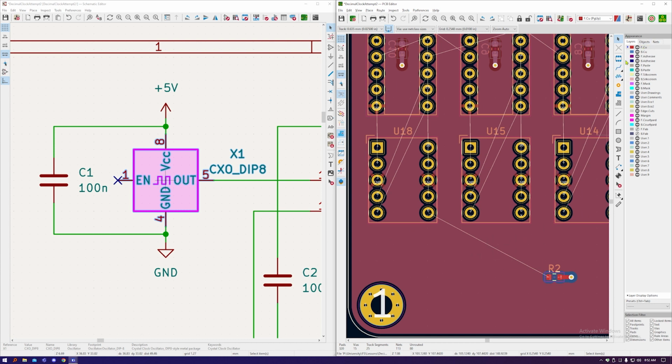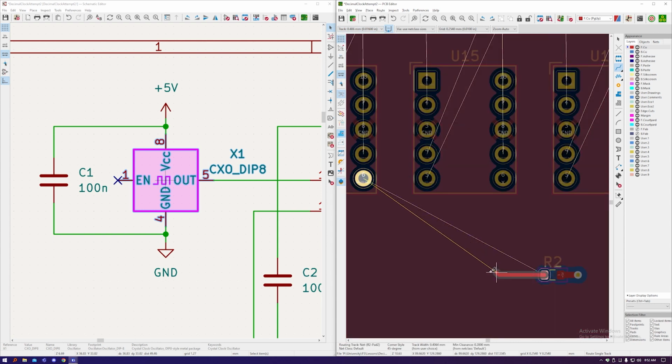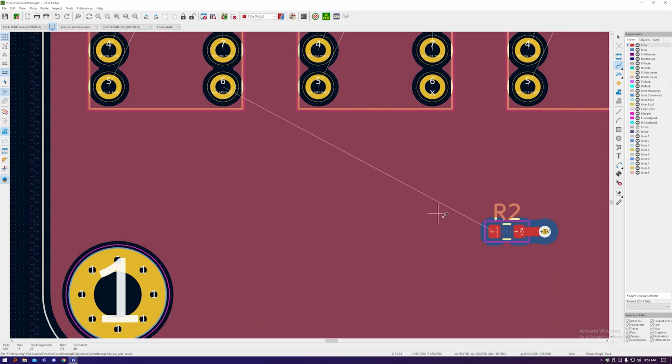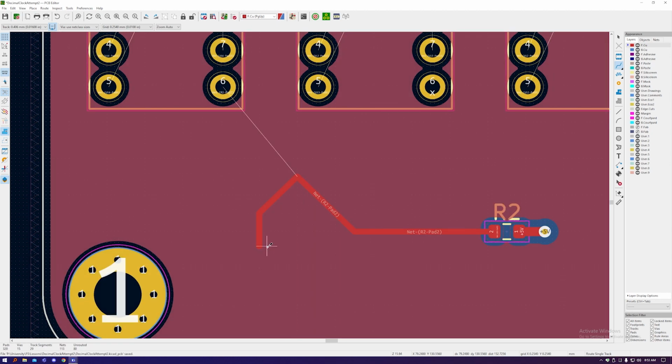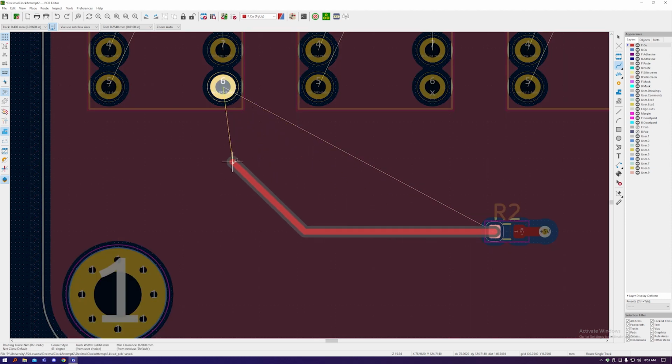On the front layer, we're going to select Trace Tool. I'm going to change the width to 16 mil, and we're going to run along here. With these ones, when you're doing the trace, when you click, it locks up to where you've clicked. So if I know I want it to definitely come to here, and then I want a forbidden right angle, then I can do that. But that's the one thing I'd say, whether you're on the race team or not, never put a right angle in your layout, or you'll be very heavily judged.